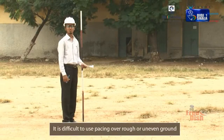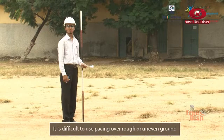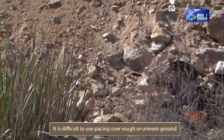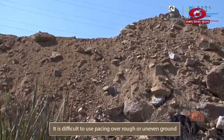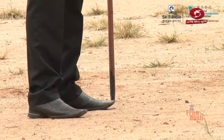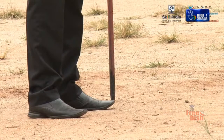Pacing can be used as a means of direct measurement when the ground is level and without any obstructions. But it is difficult to use pacing over rough ground or when the ground is sloped. So, keep in mind that pacing, which means using the length and number of paces to measure a length, is only a rough means of measurement. It is preferred only when quick estimates of measurements are required.